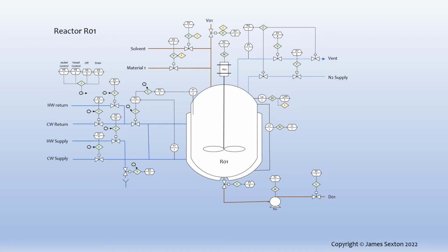It may also be useful to incorporate the control scenarios for an agitator in a compound control module. Typical commands might be off, on, time cycle or level control. The nitrogen and vent system here may also be a candidate. For example, a sequence to purge a vessel can be embedded in a compound control module. Compound control modules are useful for semi-automatic control of the plant. They're also useful for reducing the complexity of procedural control, particularly in recovery from faults, but you are not obliged to define any.